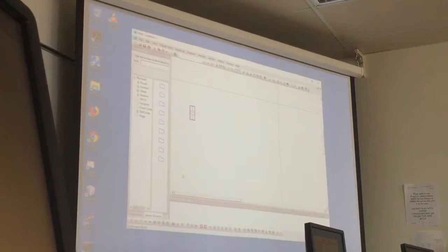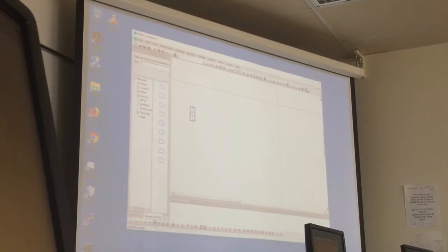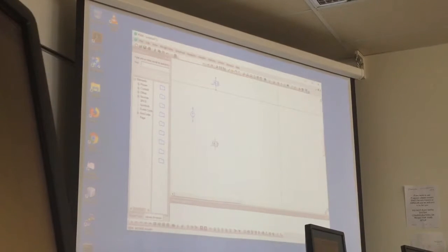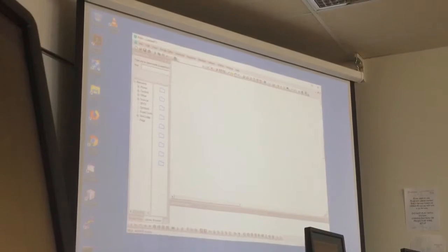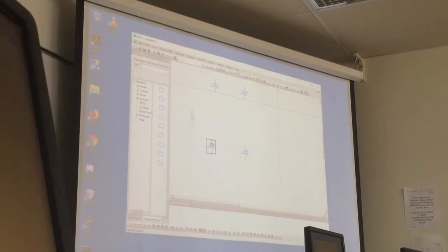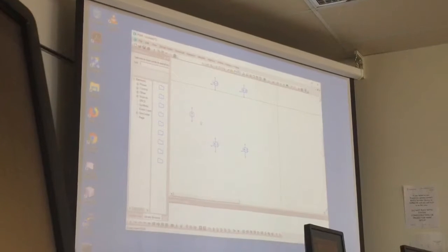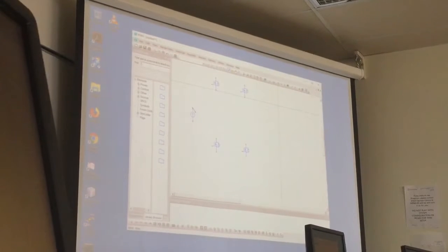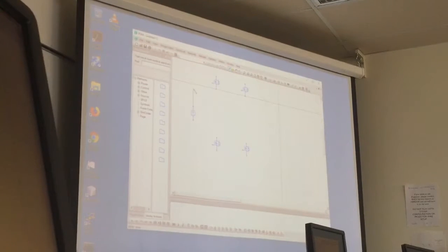And we are going to do a single phase inverter, a DC to AC converter. For this, I'll be using some MOSFETs because I plan to switch them at high frequency. So I'll be getting 4 MOSFETs, and I'll place them here on my schematic. And then to connect the elements, we just need to come here to the wire, and it's really simple. Just click on the component and drag the mouse.